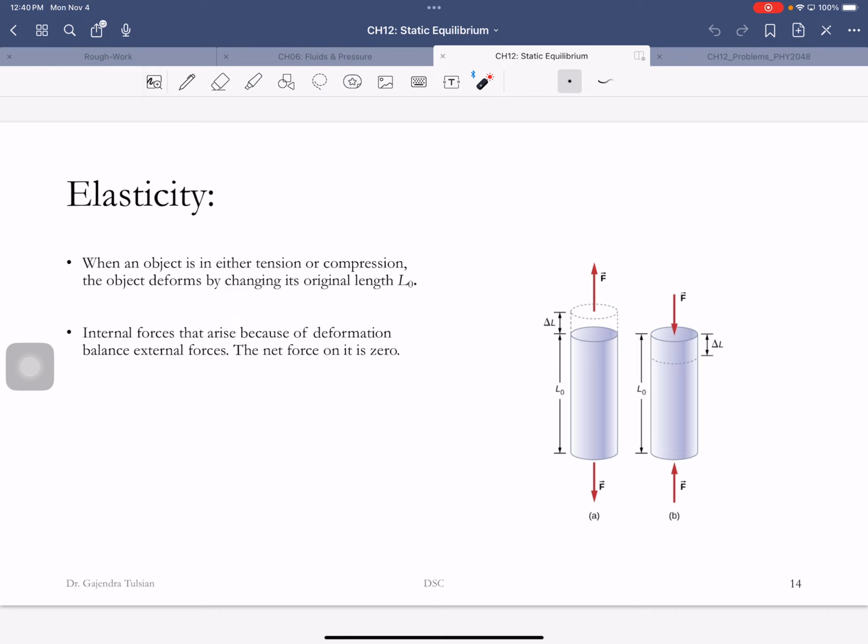So let's say, I'm just making up numbers, you hold a concrete pillar, and if you pull with a force of 1,000 pounds and it cracks, how many pounds do you have to apply to the same concrete pillar before it cracks? 10,000 pounds. So it's 10 times stronger under compressive stresses. So you keep this in mind.